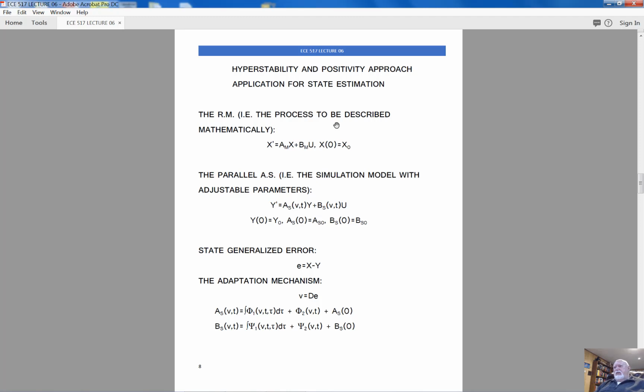What is the purpose of the system that we want to build? To get an estimate of matrix Am and an estimate of matrix Bm, and also create a system that could produce estimates for the state vector X. I want you to realize later we will be using the state vector X in the adaptation mechanism, but the adaptation mechanism very often does not require such a sampling frequency as the control loop. So we will create a way to provide information on the state vector X with virtually any desirable frequency.